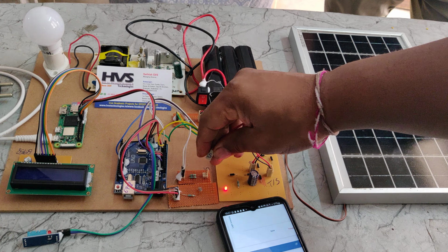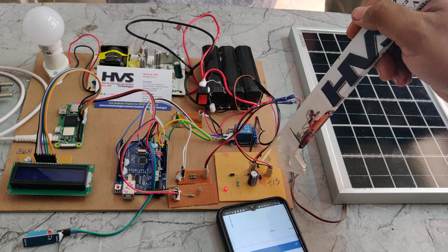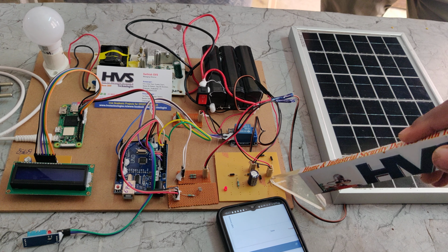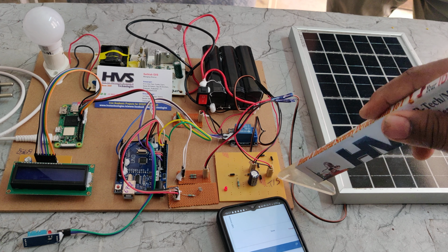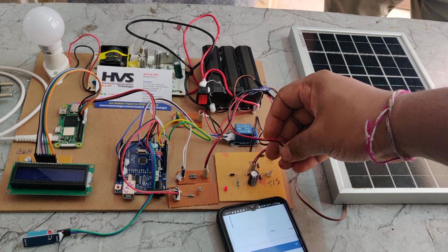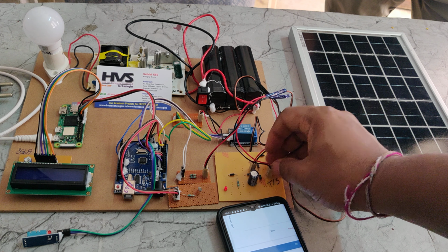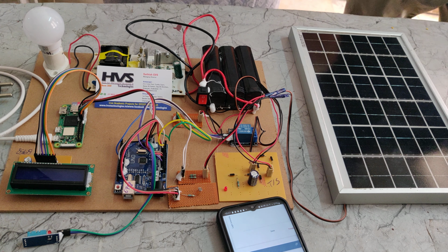So it's a solar panel and one more for the voltage sensor. So now these 4 diodes will act as a polarity corrector. When we provide the AC inputs, they are acting as a rectifier, converting AC to pulsating DC. When we connect the DC inputs, these will act as a polarity corrector. Means if we connect the solar panel in reverse polarity direction, then that will be rectified with the help of these 4 diodes. We will continuously get the DC.